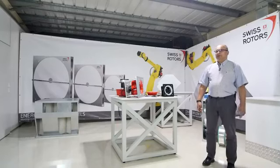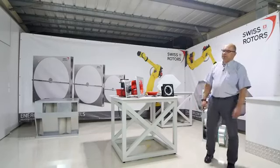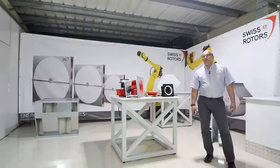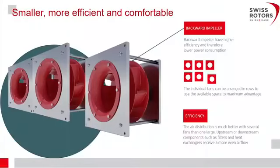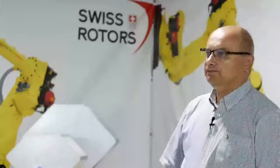Big capacity motors are much bigger, so they also require more space. After all, on the suction side we need some space to equalize the airstream. For example, if before the suction side there is a heat exchanger, in order to use the whole operational surface of the heat exchanger, there must be a certain distance from that kind of big fan. With a smaller fan, this distance could be much lower. And of course, we are saving the length of the units, the cost of the units, the space necessary, and all other costs related to a very long air handling unit.